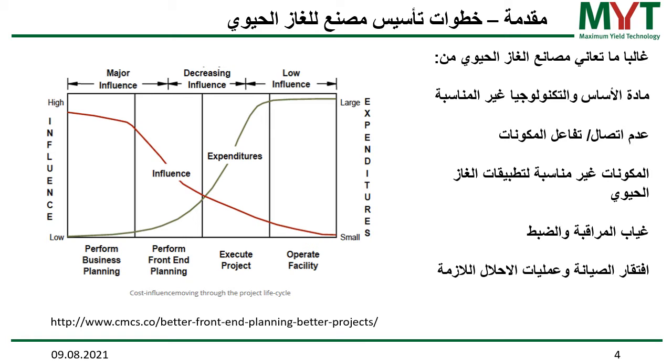Again, the example of sand or stones in the process. You might have a macerator which requires clean substrate, and if you don't have a removal system for your sand and your stones, then this will cause problems. So a biogas plant cannot be built simply by putting together some components. I think a biogas plant is all components working together and matching each other. This is very important.